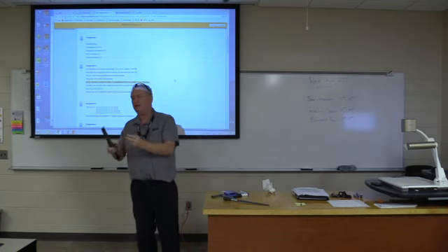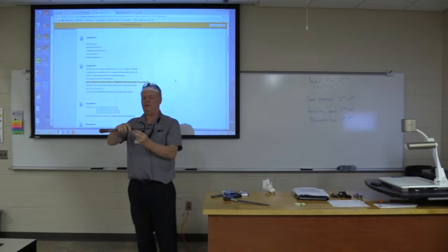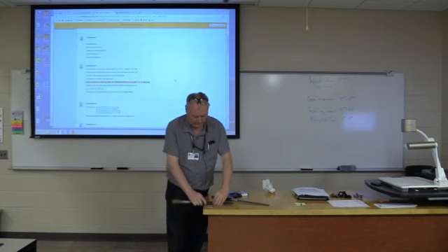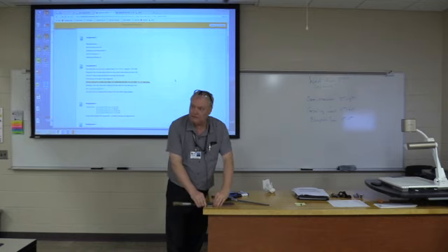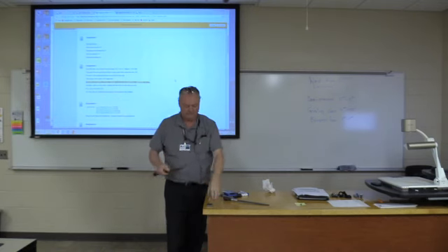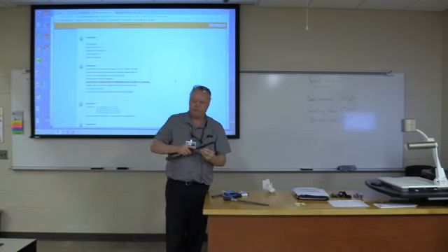Now this is a double cut file, so as far as the technique goes, some people kind of hold it in their hands, if you can see it from here, and this one can be used this way because it's a double cut. The edges are doubled. Or you can just use it in one direction.